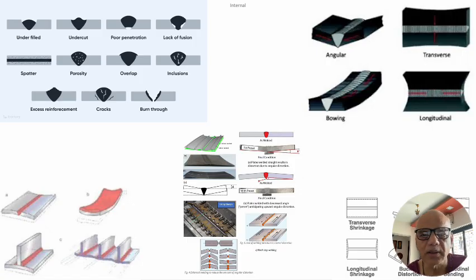But there is a limit, and finally we need to accept it or we need to correct it post welding by once again depositing extra layers so that there is a smooth transition from one side of the weld to the other side. And this is finally not a very good practice, and designers will always have a suspicion on how these products will perform, because they have taken care while designing that the mismatch and other setup defects will be at a minimum or zero. So that's the first one.